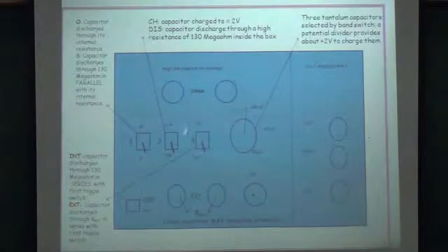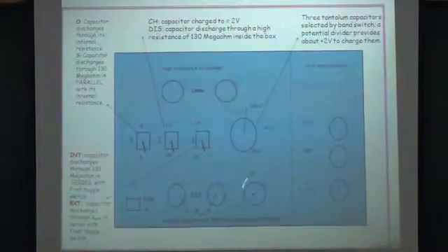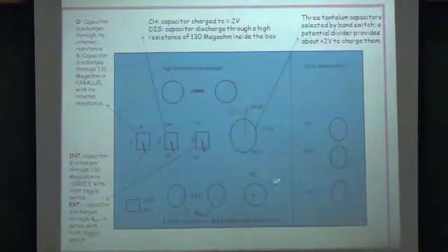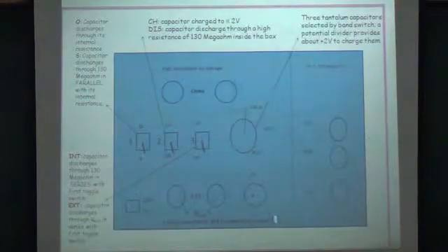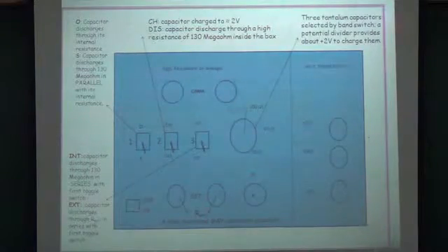Okay. Also, when you are going to measure the voltage across the internal resistance by using this DMM, there is one more switch here. This is PS. It is basically a push switch. When you are going to measure the voltage across the capacitor, you have to press this switch, and only then will you measure the voltage in the DMM. Now what is there basically behind this? This PS or press button, in fact there is a buffer circuit below this.